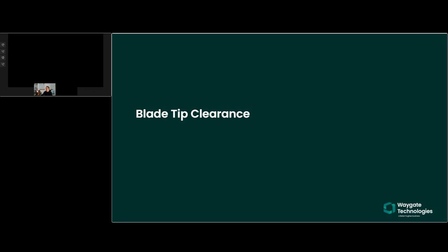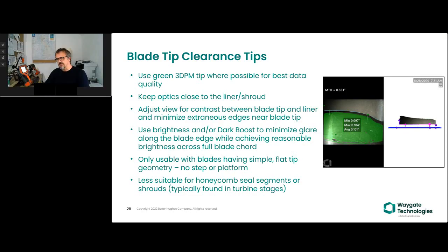Thank you, Clark. Blade tip clearance is another measurement type available to you on the MVIQ. Developed a short number of years ago, I think it was 2 or 3 years ago now. It appeared on the borescope during one of the upgrades that we had. Blade tip clearance, as the name suggests, is a function specifically designed to measure and assess the overall clearance between the gap between the shroud liner or the abradable liner and the blade tip. And it's termed BTC, blade tip clearance, on your measurement tile screen.